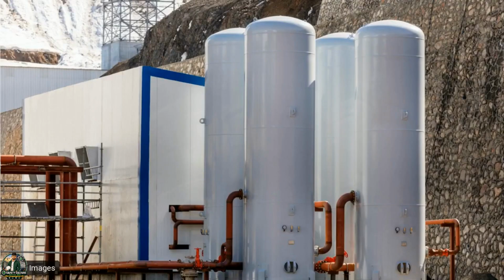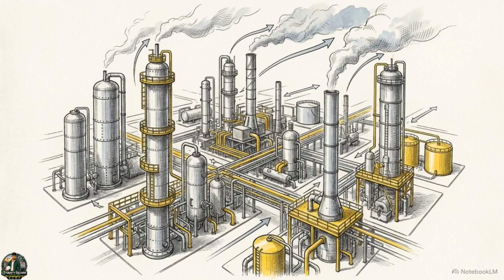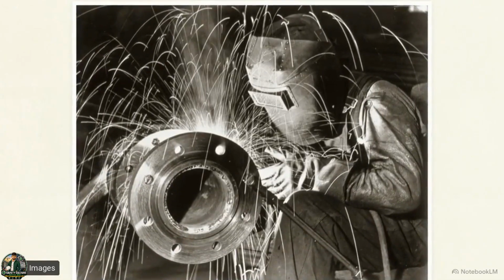The statute includes a specific geographical exception. This strict opening sequence is legally waived if the pressurized plant machinery is installed in the open air. Placing the machinery outside allows natural atmospheric dispersion to mitigate the danger, eliminating the rapid accumulation risks that exist inside an enclosed factory floor. Subsection 4 governs the application of heat.